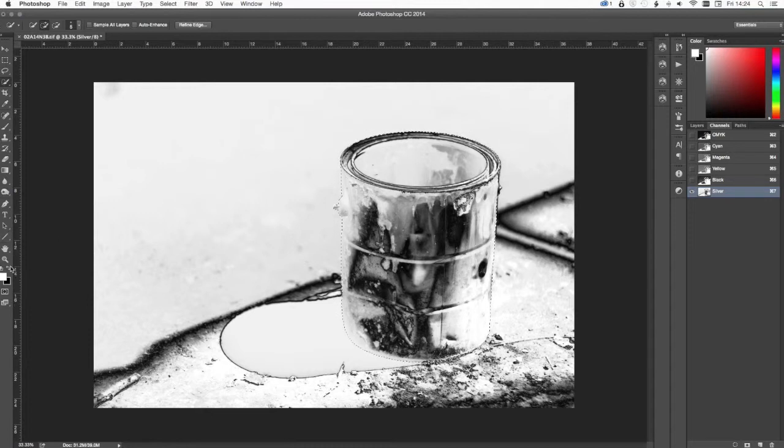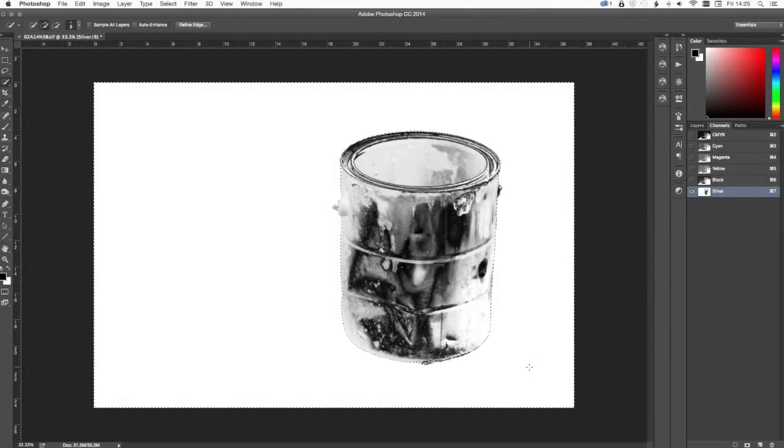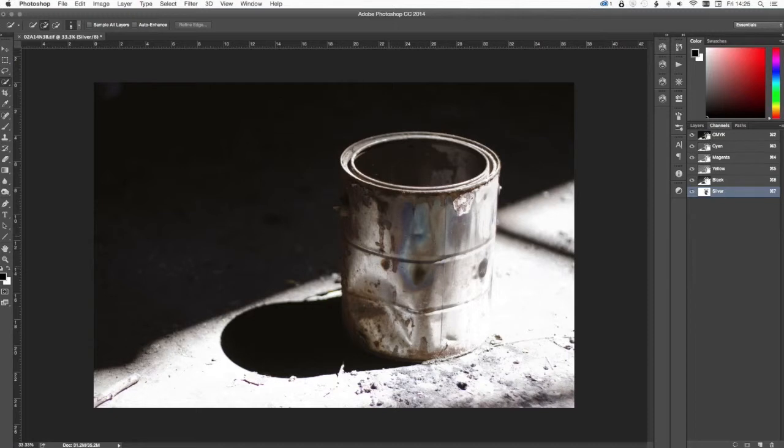And then I'm going to put my foreground and background. I'm just going to invert the mask, so now select all the background and just delete that to white. So basically delete the areas that you do not want to be metallic. You've now got contrast. You've got metallic in the paint can next to no metallic. So then the light can bounce off this and react differently and be perceived differently by the eye to what you're getting here and here.